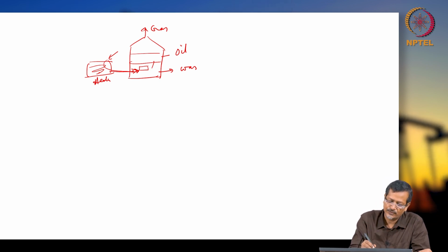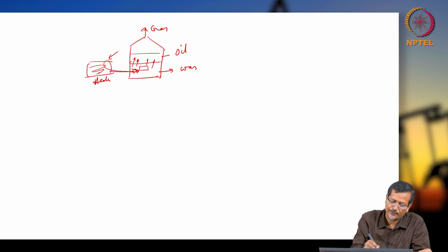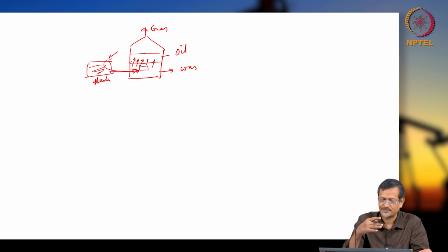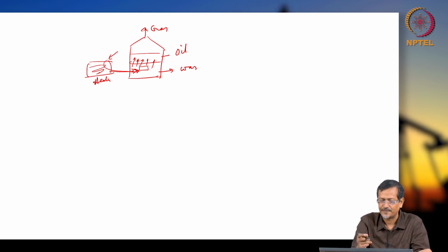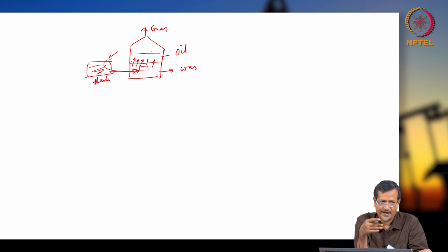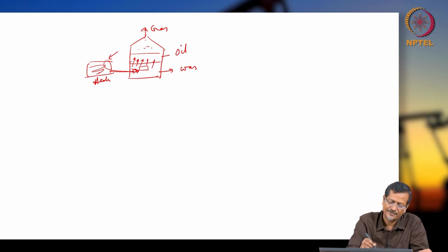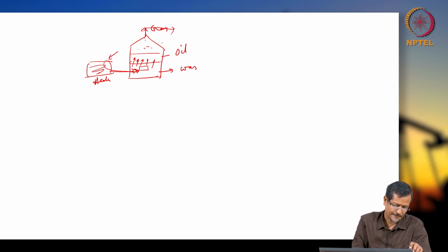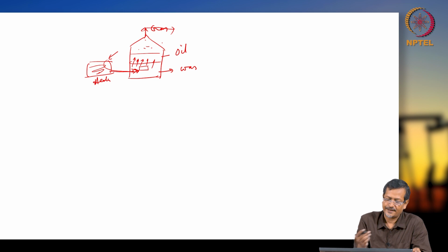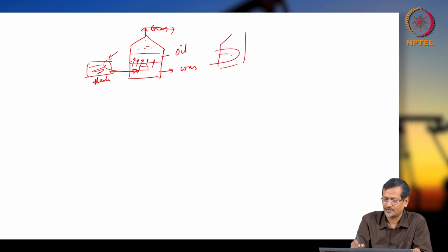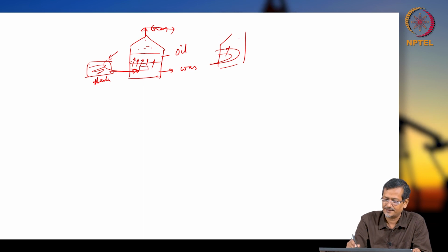Then slowly the oil particles will be moving up and up, because you changed the viscosity and density. Because of that the oil particles move up and you take the oil, and if any dissolved gas is there, because of low pressure and high temperature, the gas will go out through the top section. Fine. So this is an indirect type heater, and for a direct type heater, one possibility is you have a firebox inside and you can burn fuel and get heated.